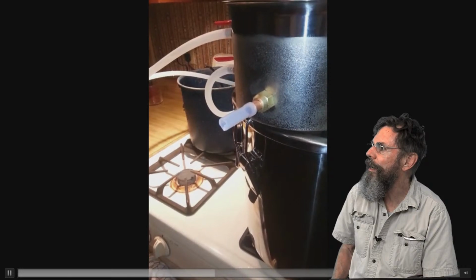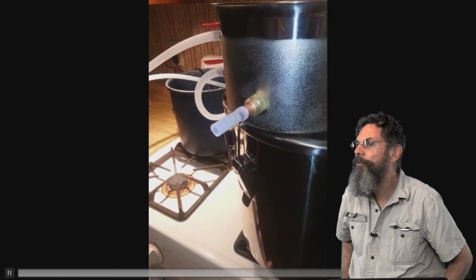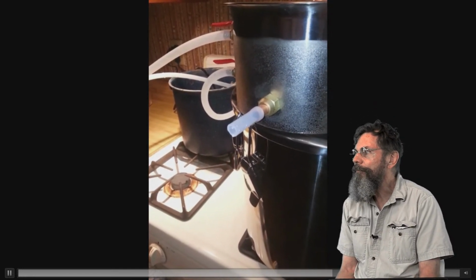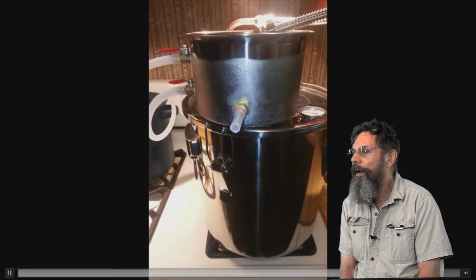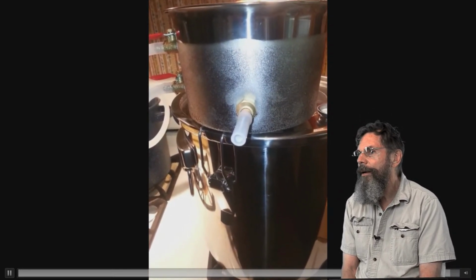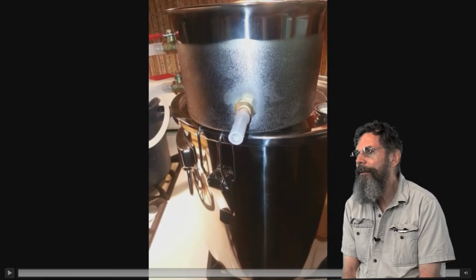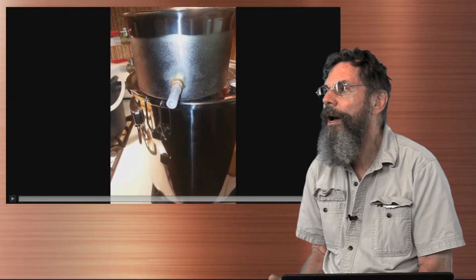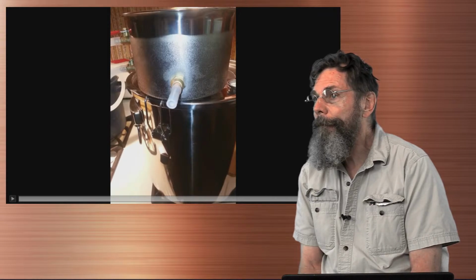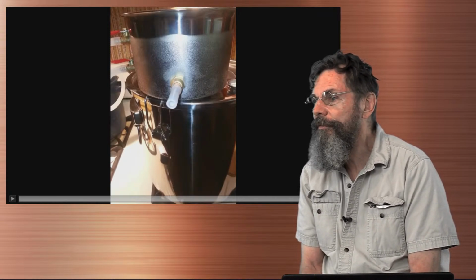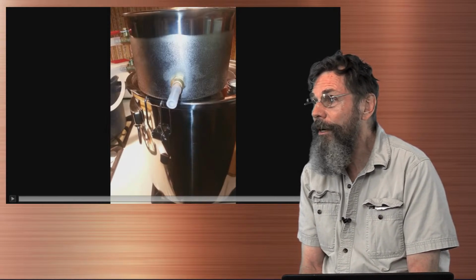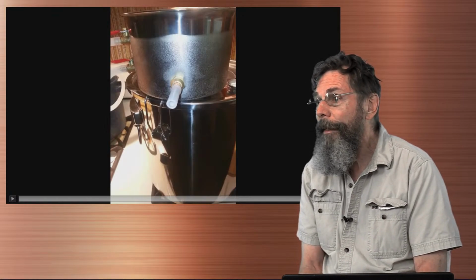It's like a real constant flow, and that's an indication of the heat being too high. And the danger of that is, it's really nice to think that you're going to get more collected water that way when it flows more constantly. But what you're doing when you turn the heat up too high is you're potentially driving out some of those contaminants that may be activated at a higher temperature, which you do not want to do. You want to maintain that as close to 212 as you can to make sure it's only water you're driving out, with the exception of, as I said, the toluene, the benzene that may or may not be in that water, but that will boil out, that will come out anyway at a lower temperature, and so you can't help that.